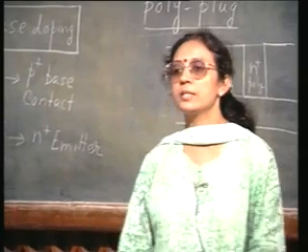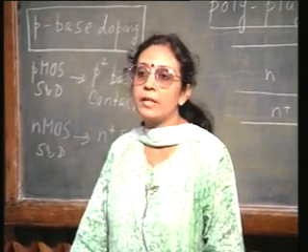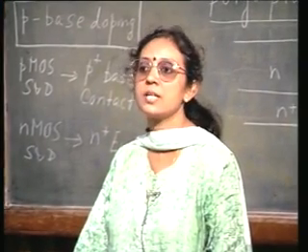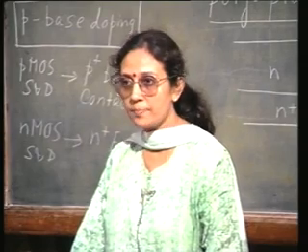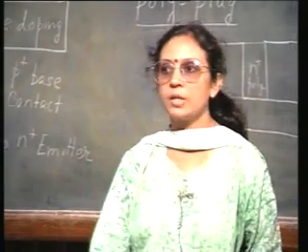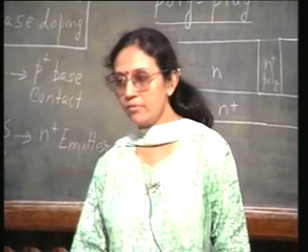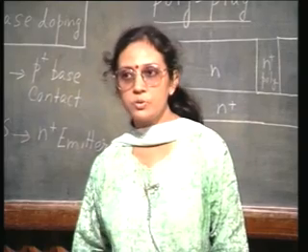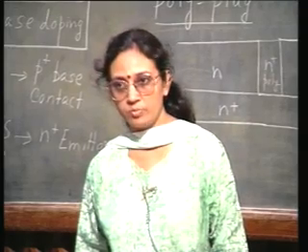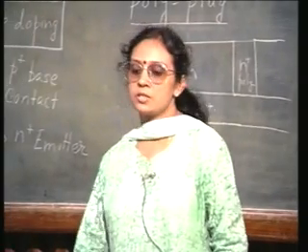And the interesting point is, as the CMOS technology becomes more and more complex, it helps in realizing a bipolar junction transistor in the same process flow. Okay? It helps to some extent because a lot of the process steps now become common to each other. So, with very few additional steps, it is possible to realize a bipolar junction transistor in the same CMOS process flow. But remember one thing, there are a few steps on which no merger is possible.